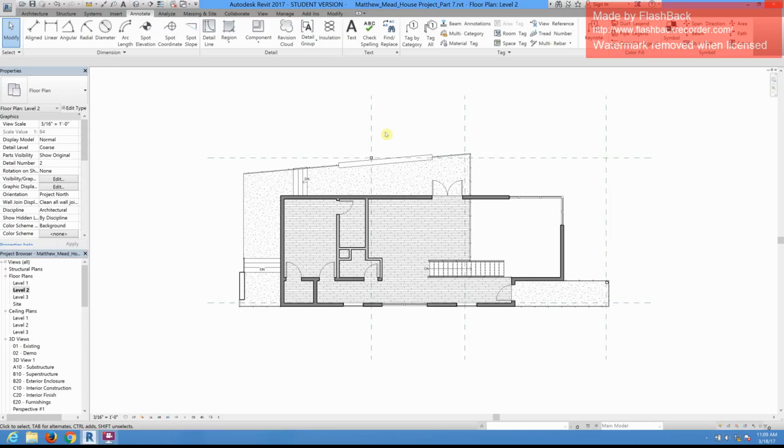You can create a template. So you duplicate that floor plan that has all of the things on there that you don't necessarily want to show. You can create a template for a standard elevation template. So you can go through and uncheck all the things that you don't want to see, and create the template.